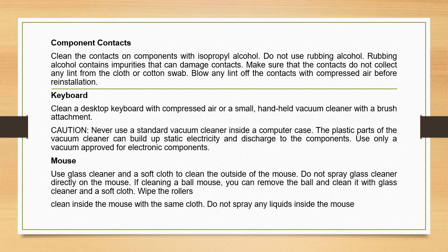Keyboard. Clean a desktop keyboard with compressed air or a small handheld vacuum cleaner with a brush attachment. Caution: never use a standard vacuum cleaner inside a computer case. The plastic parts of a vacuum cleaner can build up static electricity and discharge to the components. Use only a vacuum approved for electronic components.